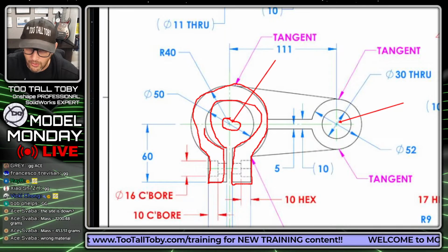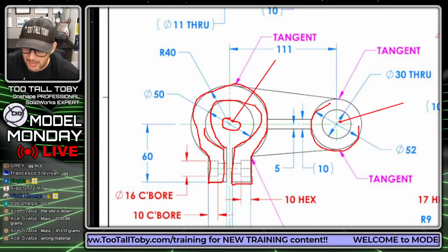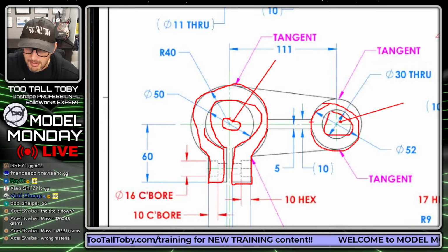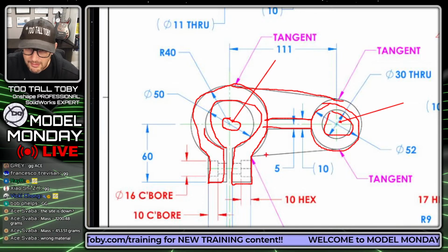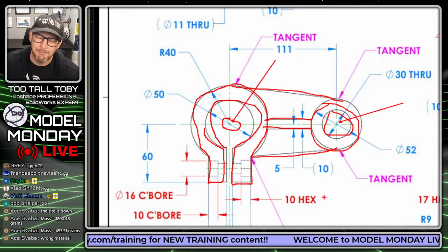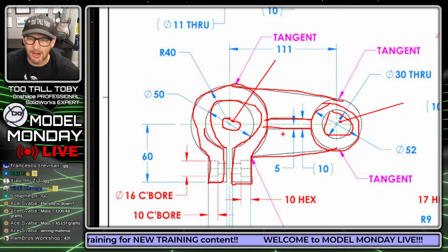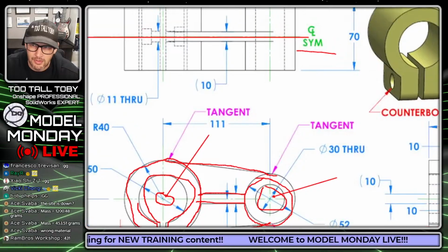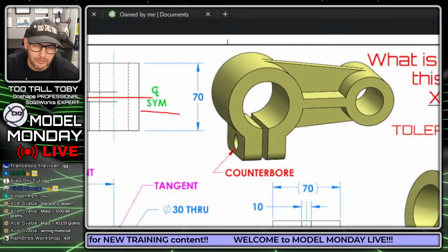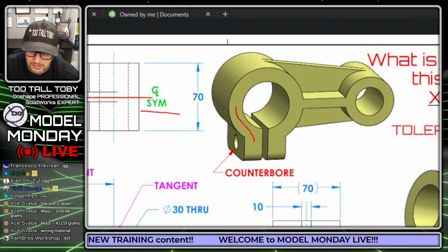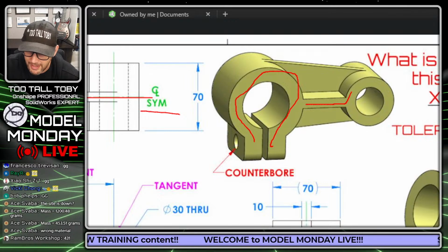It's going to contain kind of all that information there, maybe create a couple of circles over here. Maybe my first sketch will have this rib shape here, and it'll even have this shape here. So I'm probably just going to opt to include all that information right away in my very first sketch. And then once I've got all the information, I'm going to be able to extrude that information to 2 different depths. So most of the geometry, you can see kind of this whole face here is all going out to the same depth.